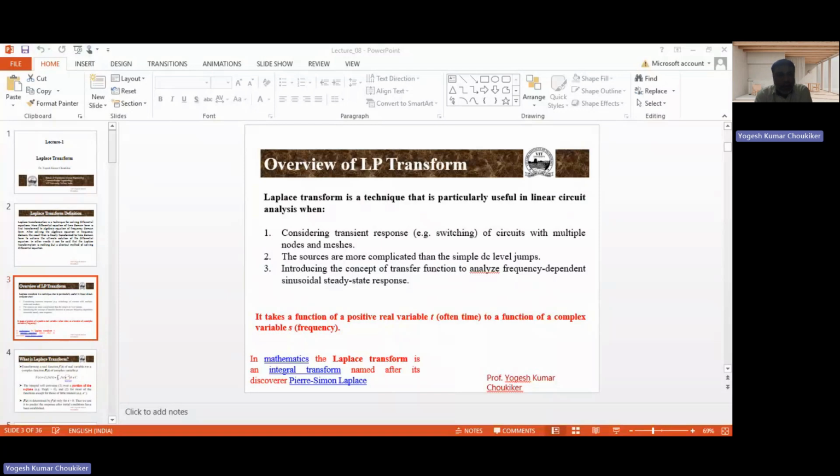So our new circuit becomes, you can see, the voltage source 1 by S. So this circuit is now in the frequency domain. Then the 1 ohm resistor, the 5 ohm resistor, then the 3 by S capacitor, then S. Our main focus is on V naught of S. We can simply use the mesh method, because we have a lot of methods. We can use node also, or mesh, whatever method you know you can apply here. When applying mesh, we have two meshes here, I1S and I2S.